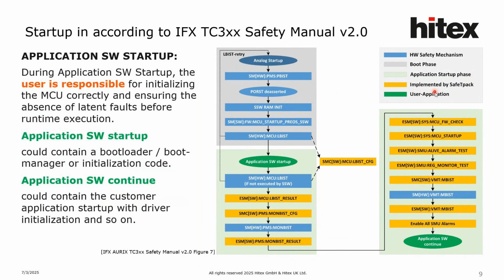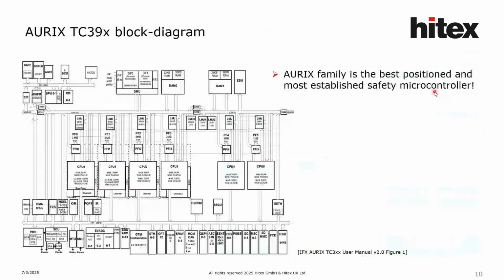Let us take a look into the AURIX block diagram. Here we have the umbrella device. Our safety mechanism can report faults to the safety management unit, with the abbreviation SMU. Lockstep mechanism and ECC protection help to ensure safe computation. Also, hardware diverse modules are available directly within the AURIX. You can imagine it is a very powerful safety microcontroller, and the AURIX family is the best positioned and most